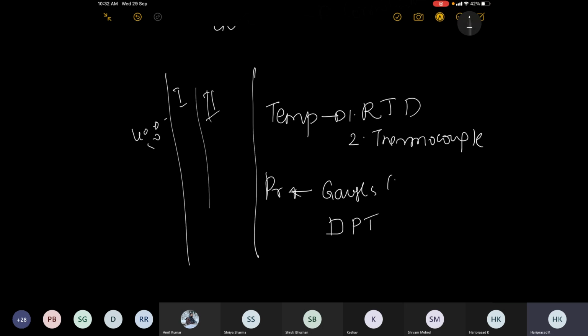The whole range of temperature that you need to operate is available in the data sheet from the vendor, or the company that makes the RTD, and you'll have to go back and check. So you state that specification to the market, and they would get it for you. Otherwise, if you just say 300 Kelvin, they might not understand, because these are all done by sellers, right? They are not really interested in learning the technical specification. They will only take a specification and give you the product.